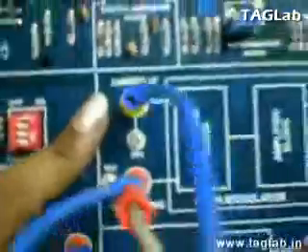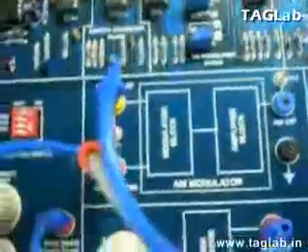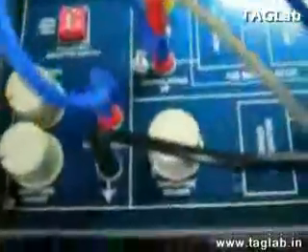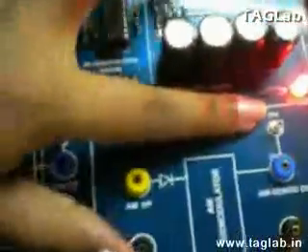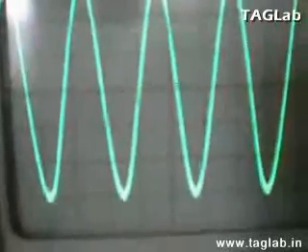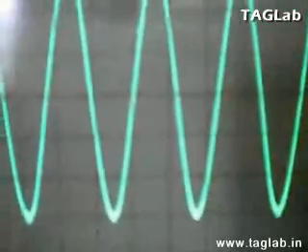Now first let's see the modulating signal. Switch on the kit. The power LED glow indicates the turn on mode of the kit. Now since we have seen the frequency is 2 kHz, on the CRO we could see that's almost 2.45 blocks into 0.2, which makes it approx 0.5 milliseconds, which is approx 2 kHz.